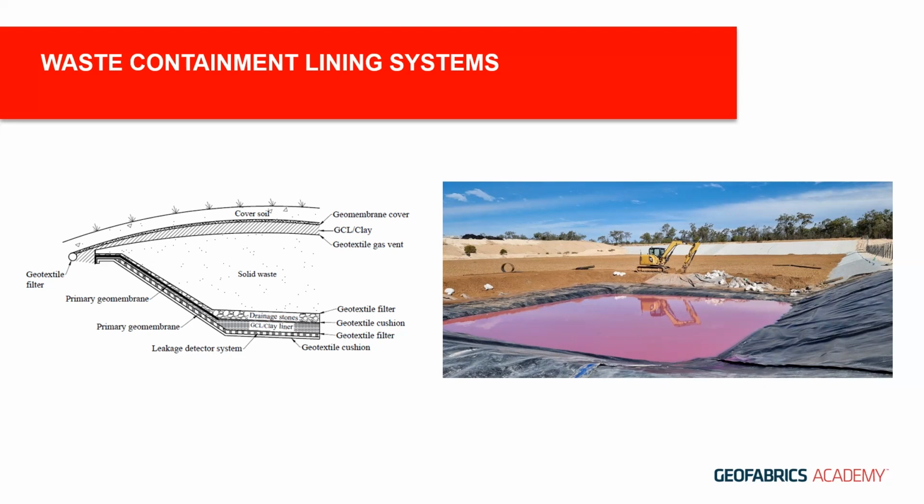When this void is eventually filled with waste, the pressure of that overburden acts on the lining system, and the protection efficiency testing ensures that the system is replicated in the lab and the most appropriate cushion is utilized for limiting strain on the HDPE geomembrane.